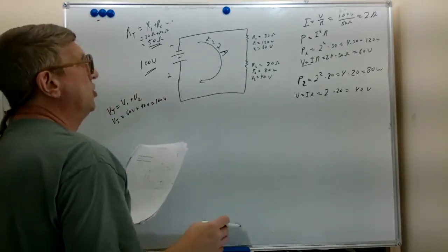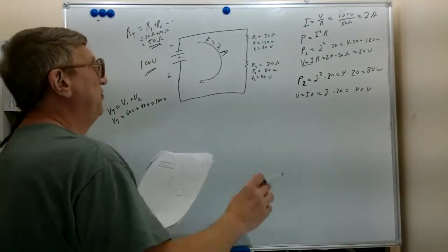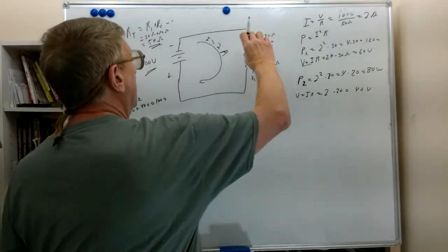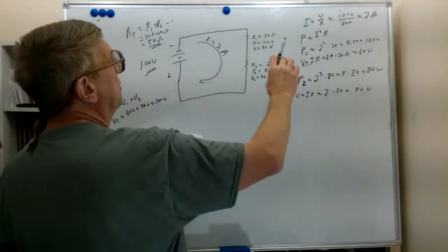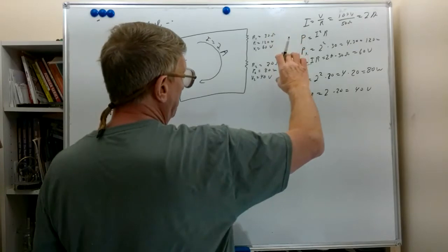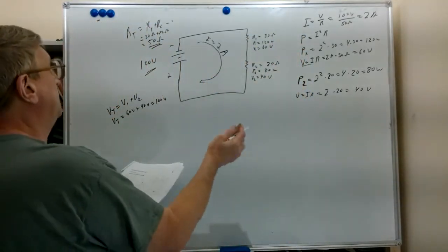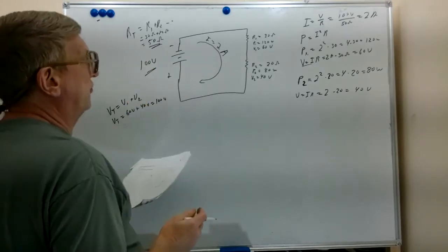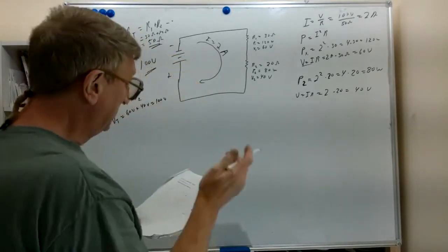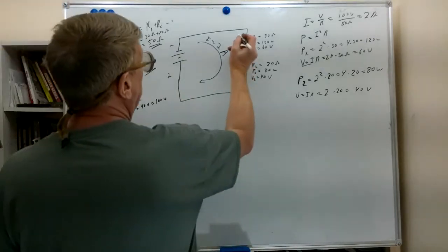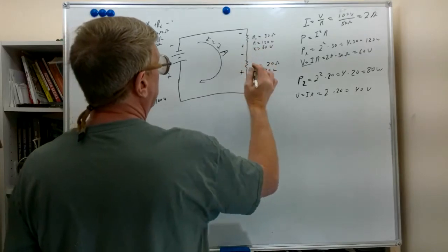So sometimes we talk about these voltage drops, IR. We will say that the voltage drops are equal in sum to the voltage sources. We have 100 volts here. We have a voltage drop of 60 plus a voltage drop of 40. That's 100 volts of voltage drop. It's equal to our voltage sources that we have in this particular circuit. And of course our polarities, like we talked about before, plus, minus, plus.